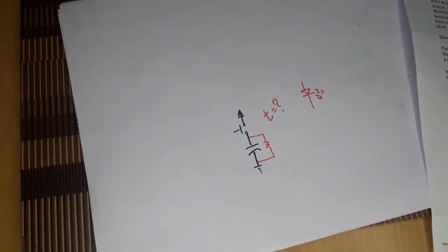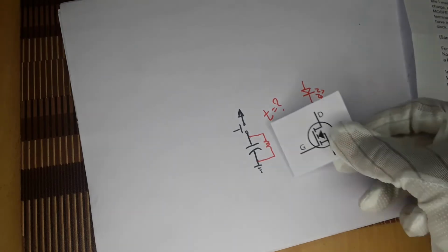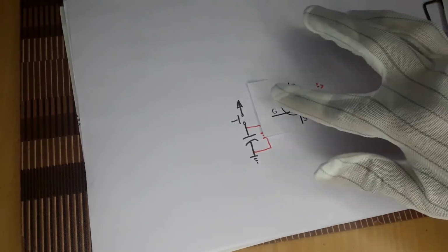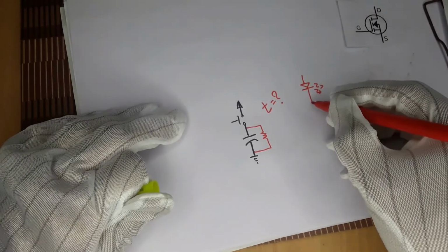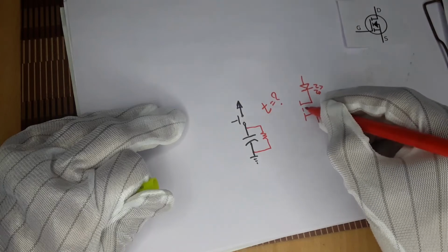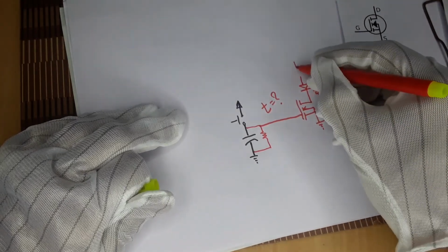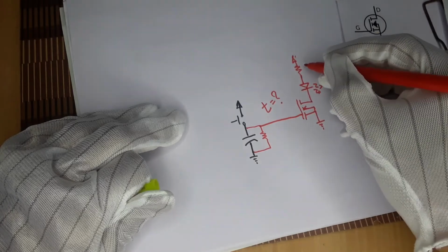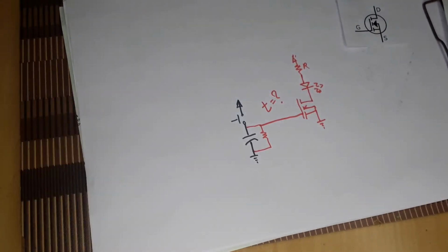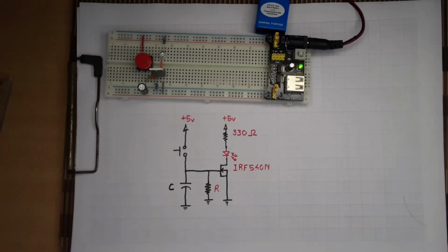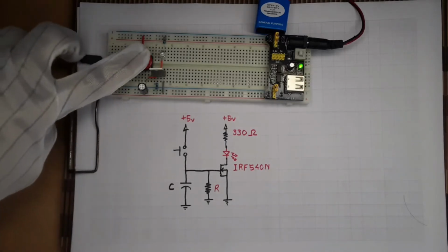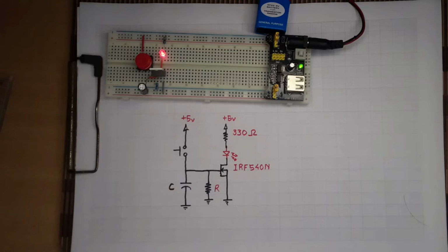And what was that, that takes just the voltage on its terminal to switch a large amount of current flow? Yes, a MOSFET. And it turns on and stays on for voltage above 2 volts. Let's add this to our circuit: an LED to indicate the output, a resistor to protect the LED, and we have our simple delayed off timer. Let's test it with a few different values of resistor and capacitor and compare them with our equation.